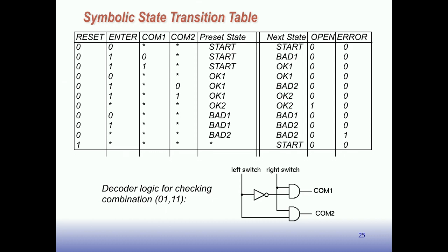Switches and buttons do bounce. If you look at the waveform coming out of the switch, it is kind of a noisy thing. So you'd have to clean it up somehow. The easiest way to clean it up is with a clock signal. So, to answer your question, buttons and switches are pretty noisy. You don't get a nice clean transition. You get kind of a bouncy, noisy thing.